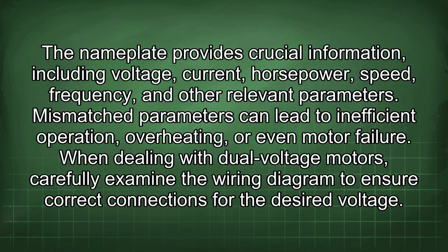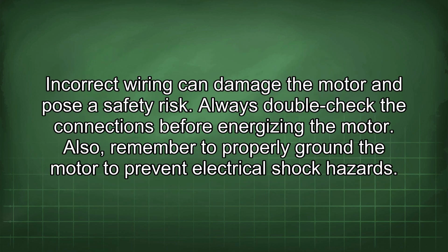When dealing with dual voltage motors, carefully examine the wiring diagram to ensure correct connections for the desired voltage. Incorrect wiring can damage the motor and pose a safety risk. Always double-check the connections before energizing the motor.